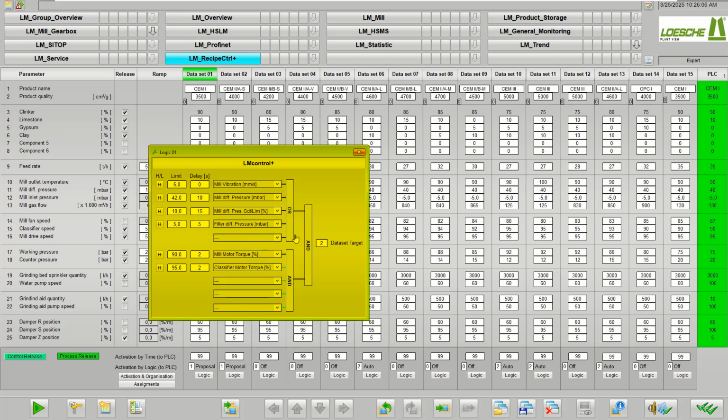The queries can be based on OR and AND combinations. The third gate can be set to either OR or AND as required. We now fulfill the logic by lowering the vibration limit. The actual vibration value is simulated and is 3 mm per second. In this case, we change the limit to 1 millimeter.